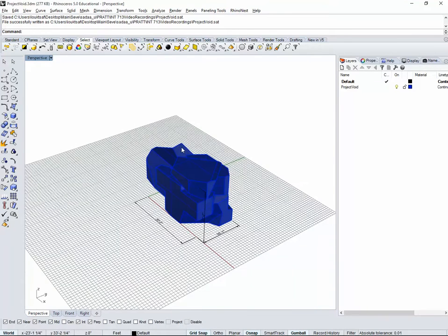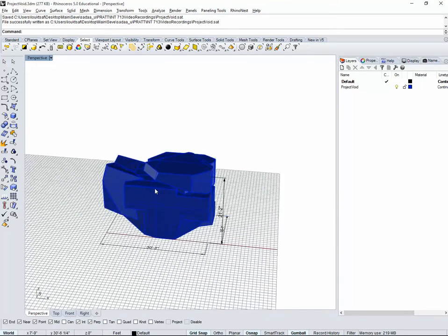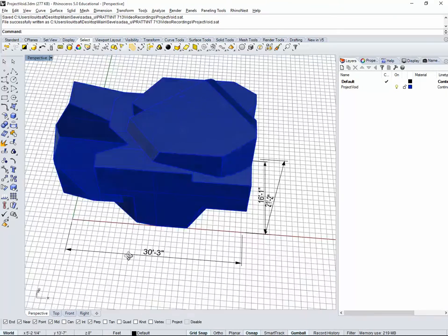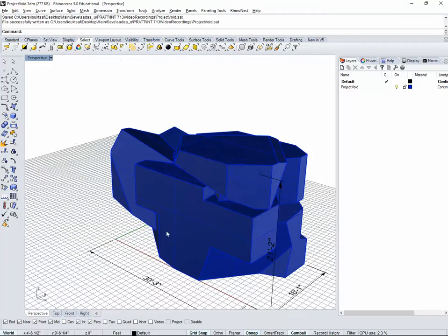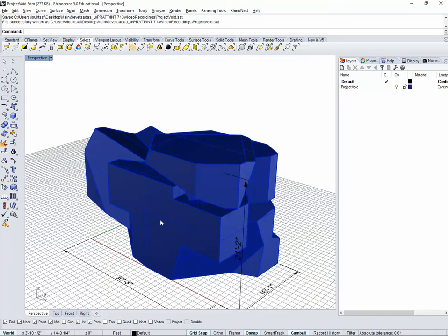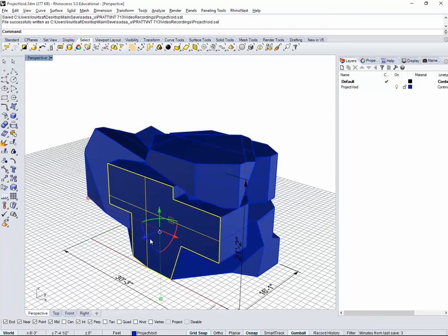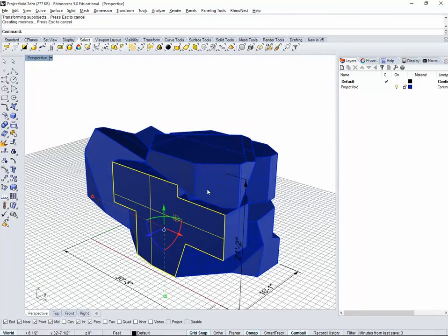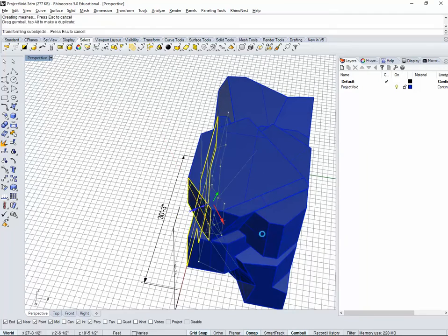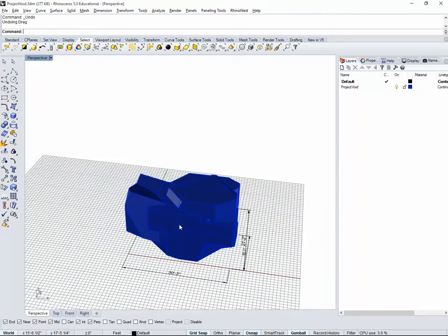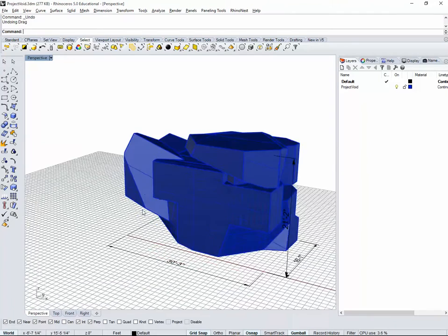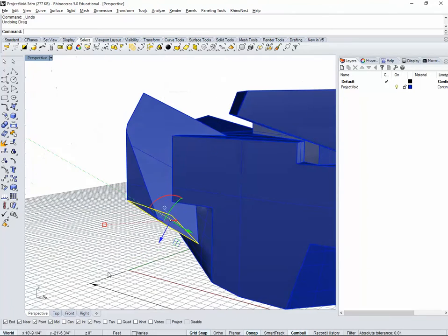And in theory, we don't need more of Rhino. We should be pretty much done here. It could happen then when you're back in Revit that you say, I wish one of the planes was a bit higher or lower. You can always just edit. You can press Control Shift and select one of the faces and move it slightly, and start deforming some of the components or doing another Boolean difference or intersection or whatever condition to change and modify some of the conditions of the model.